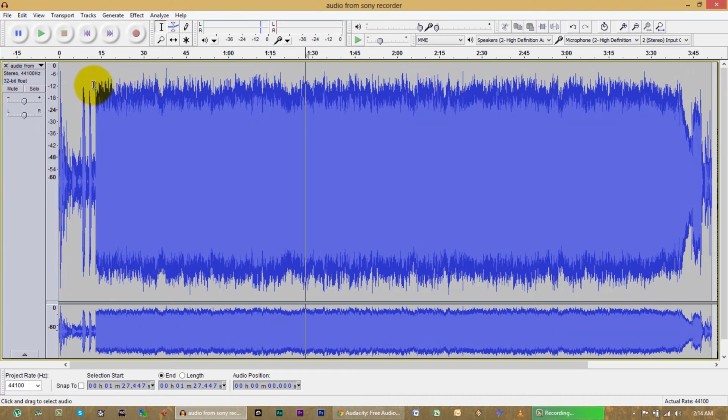But for now, I'm going to show you a quick and dirty method of doing some sort of semi-compression, semi-limiting, semi-normalizing of this file. Okay, so I'm going to pick the line straight across here where most of the peaks are hitting. It's kind of thickest around there, like say at minus 9, maybe.